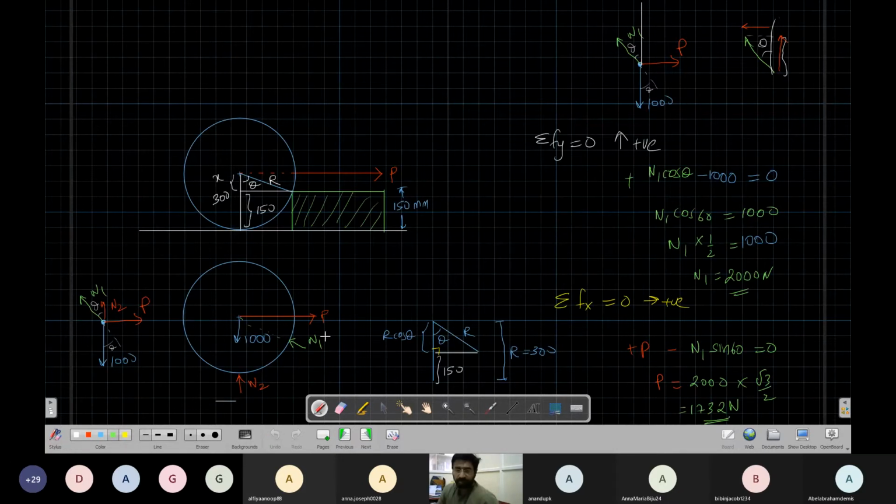So there are two confusions here. One, you have to understand the movement of the ground, and once you understand the movement you can easily do that. Now, the property of this contact force is that if the contact is gone, the force also vanishes. If the roller rolls and the contact is lost, there will be no force here also. So that also you have to see.